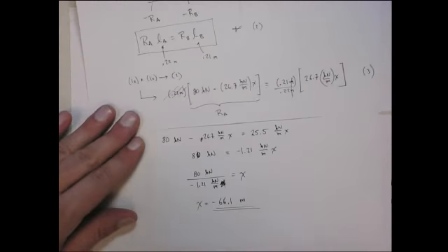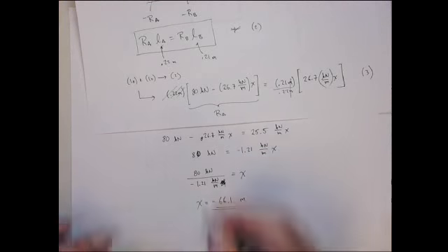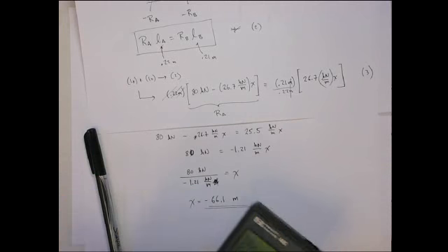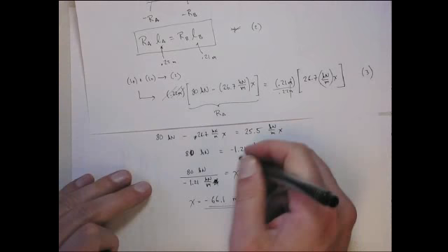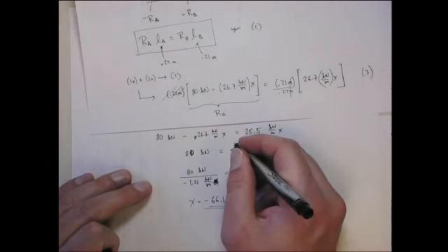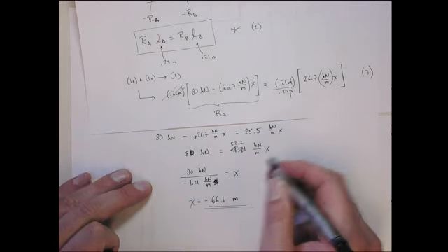So obviously what I did here was I subtracted this, but I needed to add this to both sides, right? This was a minus, so I add that. I took a subtraction, and that's what screwed me all up. Flip the sign. So when I add the two, it gives me 26.7, enter, and 25.5. Add the two. This should in fact be 52.2 kilonewton meters times X.